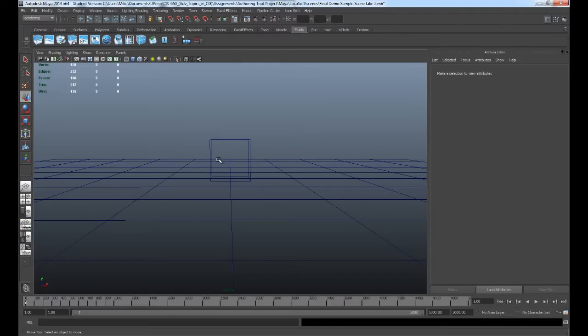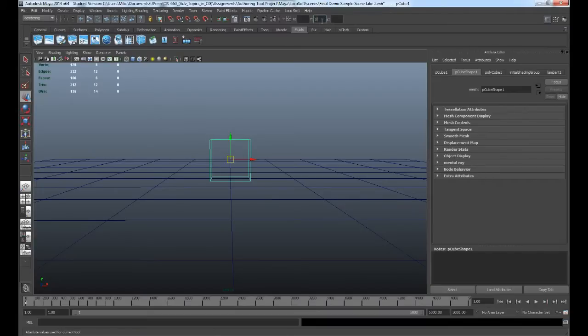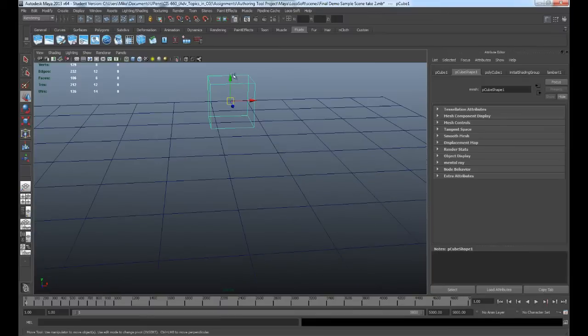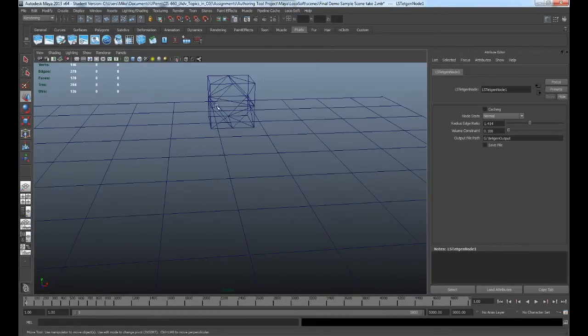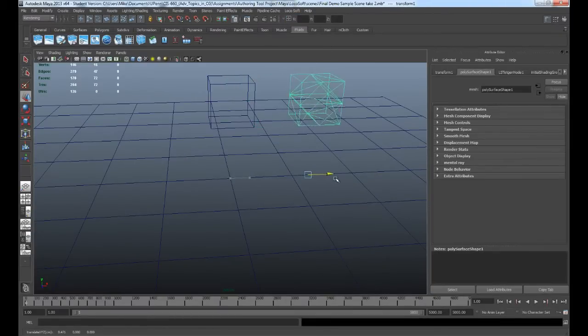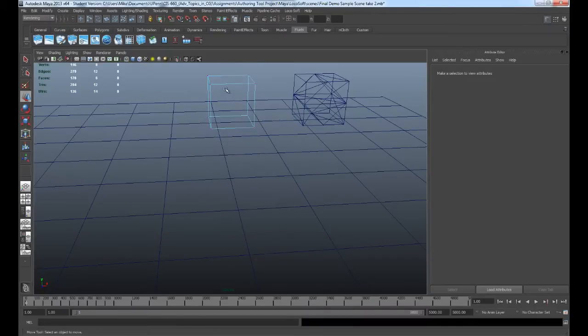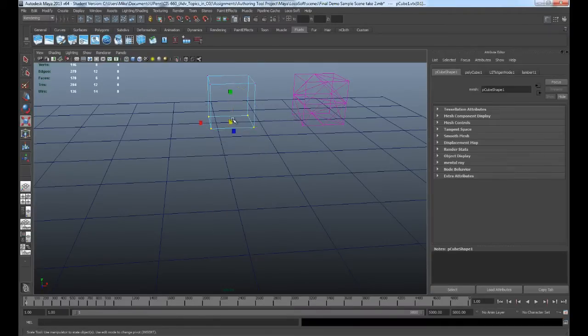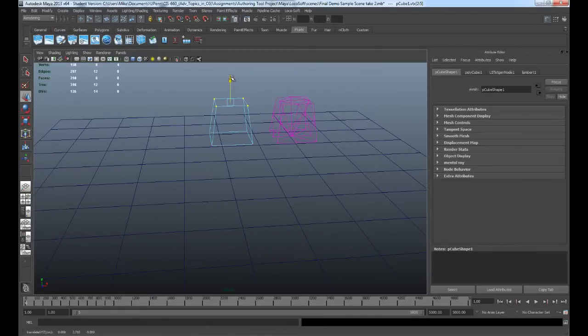We have prepared a sample scene with a polygonal cube and a ground plane. Now we are going to show you how to deform this cube using our system Locosoft. First, we are going to tetrahedralize the cube using Locosoft's tetrahedralize feature. Once we have this tetrahedralized geometry, we are going to show you live tetrahedralization. So for that, we are going to deform the original mesh. We are going to choose vertices, and we are going to increase the base a bit wider, and we are going to increase the height. You can see the tetrahedralized geometry change on the fly.